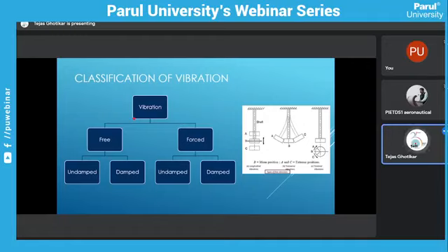That is the reason behind the decay in vibration, and that is nothing but damping. That is a natural damping on the system. So damping is always there, and in practice we cannot have an undamped system. We will always have a damped system. Damping absorbs the vibration.